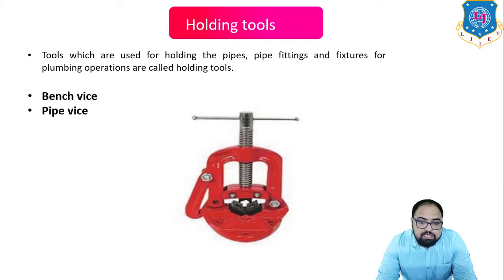The pipe vise is a tool which is used for holding a pipe to carry out assembly, disassembly, threading, cutting, etc. The pipe vises are mostly of two types: open type pipe vise and fixed size pipe vise. The standard sizes of the vise are 18 mm, 105 mm, 130 mm, 170 mm, etc. as per the open size of the jaws.